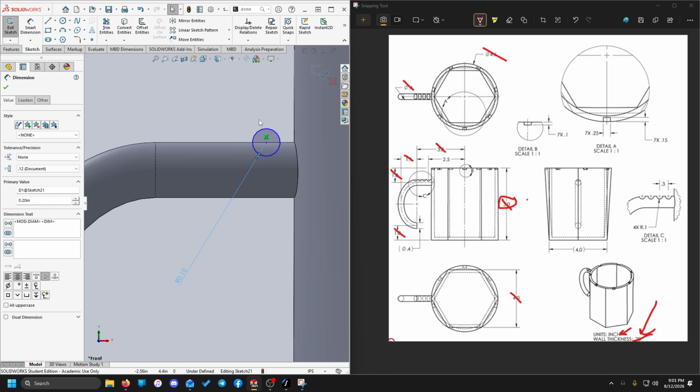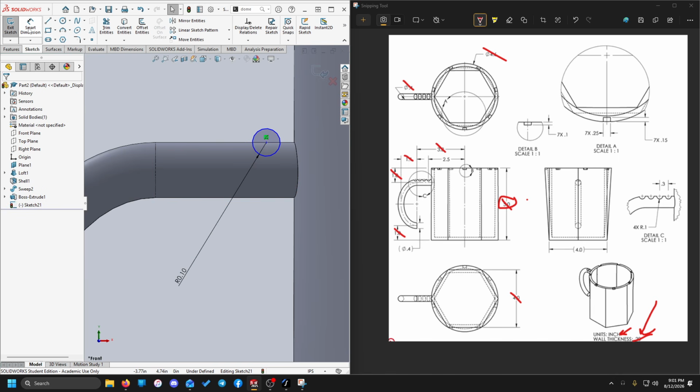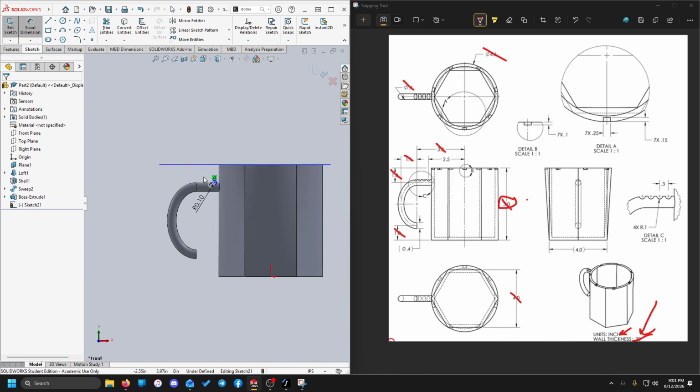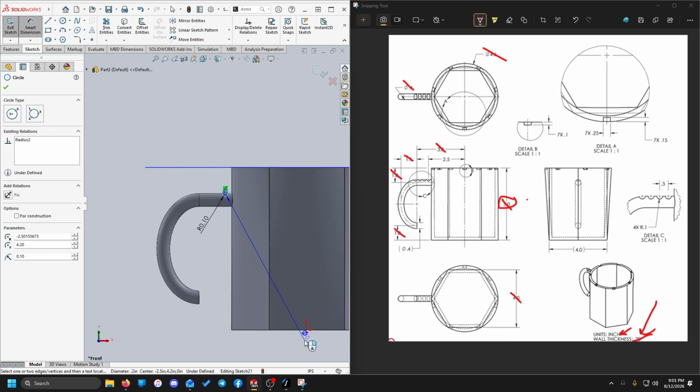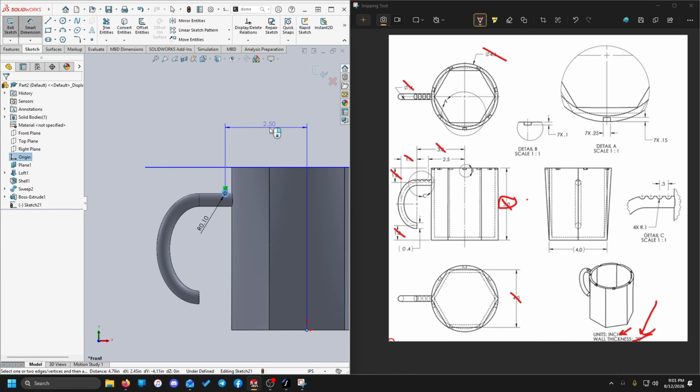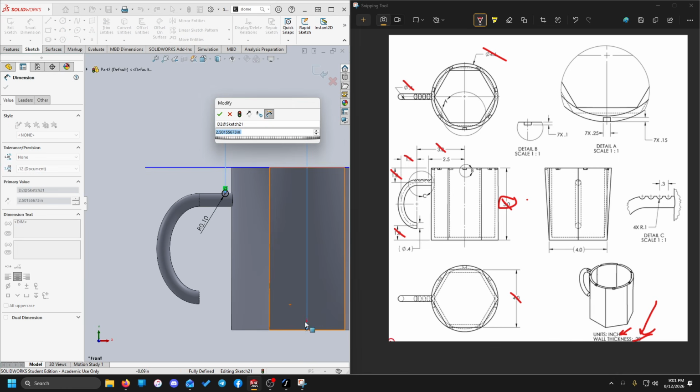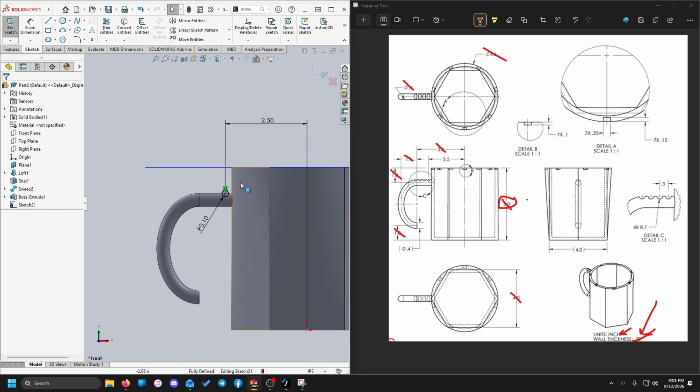I'm doing it as a full circle just because that's marginally easier than doing it as a half circle and then getting all of that defined. But you could also do this as just an arc with a horizontal line to cap it off, and then dimension as needed. But we've got our circle, and then our horizontal position is going from the circle to the origin, 2.5 units.